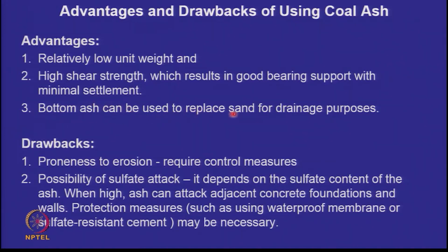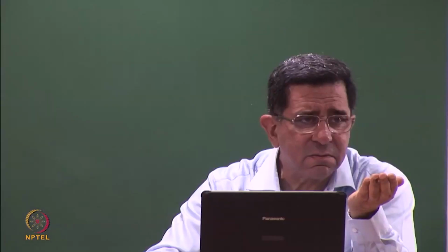And bottom ash can be used to replace sand for drainage purposes. With all these interventions of the courts on mining from riverbeds and crushing of rock, availability of sand for drainage purposes is very, very low. So, a lot of pressure to use bottom ash to replace sands.